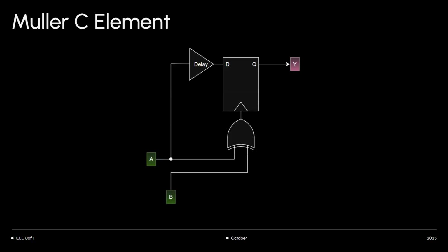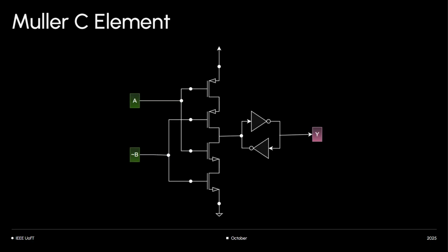Okay, so this is a practical circuit that you can build. If you want to build it with MOSFETs, go for this. Each of these AND gates, NOT gates, will be expanded into how many transistors? 2 transistors. So that's 2 plus 2, 4 transistors, and this is 4 transistors. This is an 8 transistor implementation. Okay, and this is the original implementation that Ivan Sutherland proposed in his paper. So just for your reference.